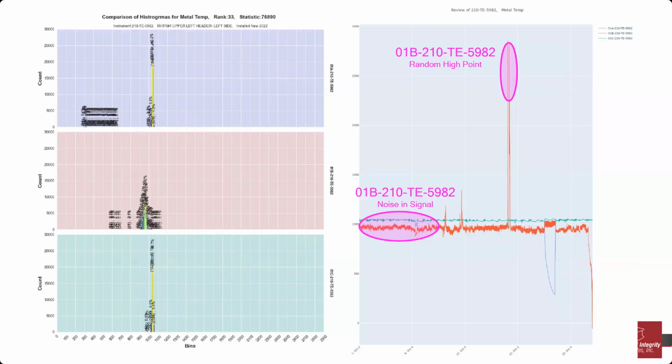So that certainly plays into it, but we're following the same basic process with installing instrumentation and using Structural Integrity to monitor that, using their PlantTrack data. And as far as the age, it is going to be a little more tricky getting some of the historical data because we have to go back almost 20 years versus 10 years with this other plant that we're monitoring. So that all kind of factors into it. And then you have to make some assumptions for the components where we haven't added additional instrumentation, but you can keep those assumptions on the conservative side. So therefore, you would detect the damage before it fails.